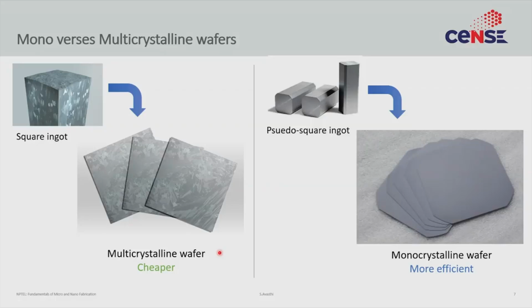If this is not making sense, give it some time. I'll show you the full module and we shall discuss this fill factor part. So what people do is take that cylindrical wafer and not exactly make it into a square, because that would waste too much material, but make it into what is called a pseudo square. It has these rounded edges, if you notice. It's still relatively squarish, but with rounded corners. So both of these exist. Both of these are often used to manufacture silicon solar cells.